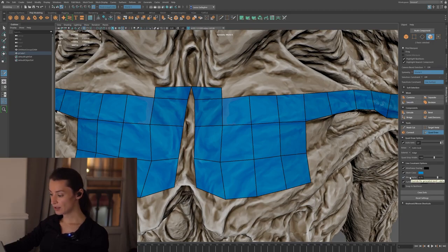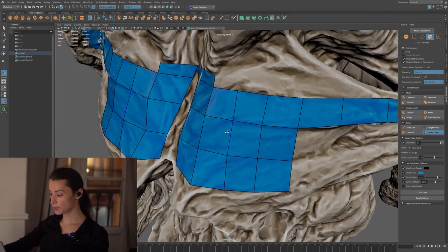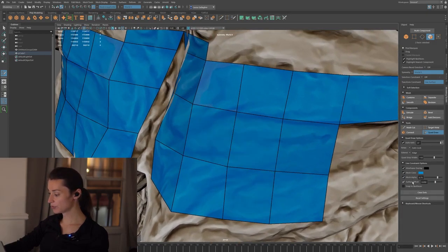The mesh alpha is the fact that we can kind of see through the mesh a little bit, of course. And the surface offset, this one is interesting. I'm not sure what the default value is, whether it's 0.05 or if that's me that set it to that particular value. But it is very good to keep a bit of an offset there.